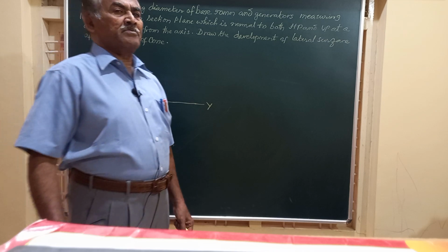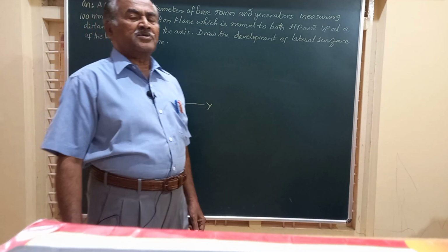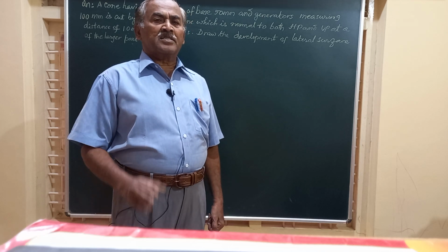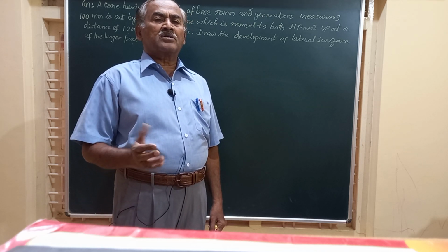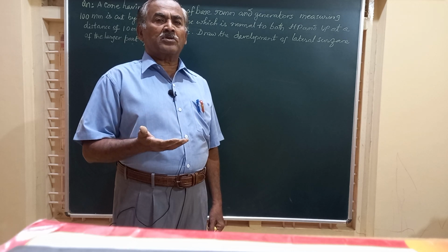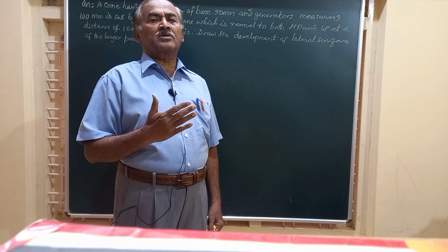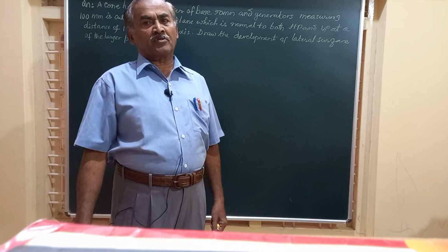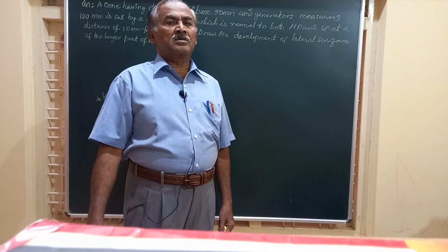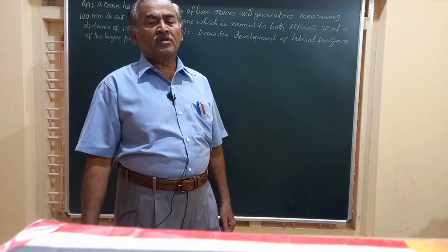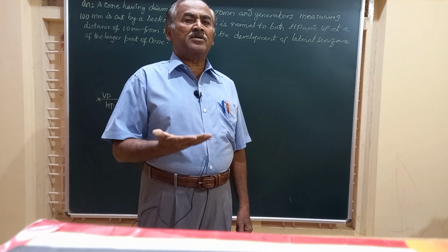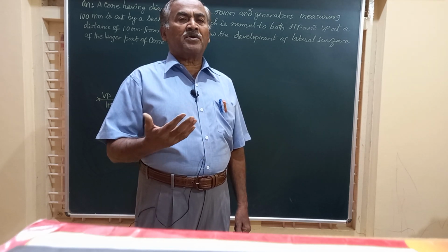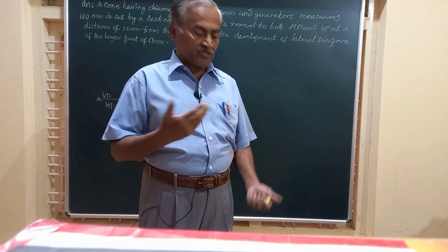Myself, Dr. M. H. Channaya, and in today's session, we are going to study the development of a right circular cone which is cut by a section plane which is perpendicular to both HP and VP. So, friends, basically in this problem, we have to place this solid on HP on its base, get the top and front views of the cone to start with.